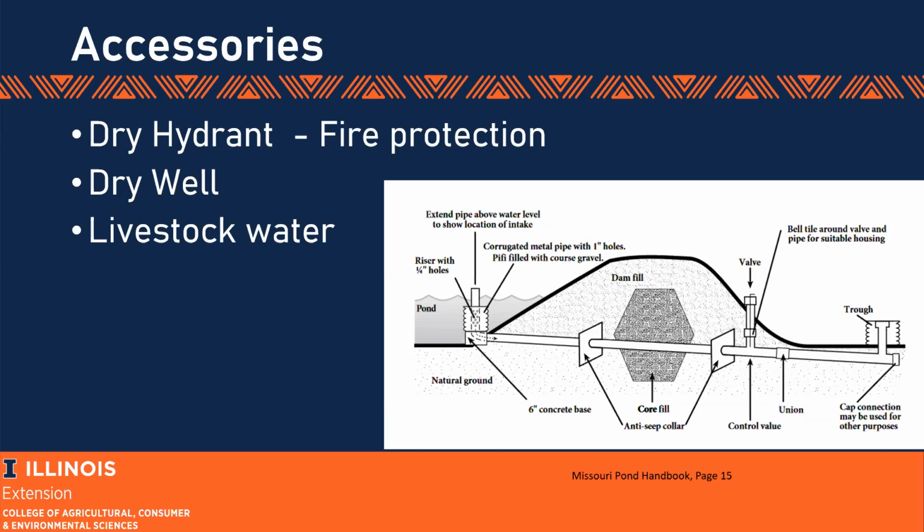But just as you would the pipe for your spillway, it needs to be put in with the anti-seep collars and through the core of it, so that you don't open up a pathway for water to get through and cause problems later.